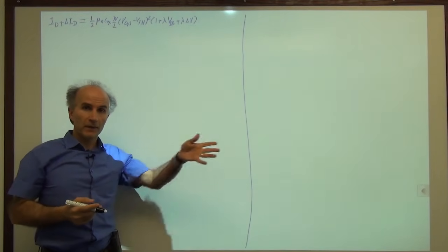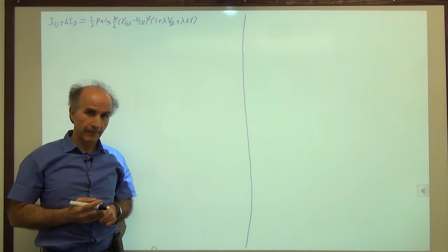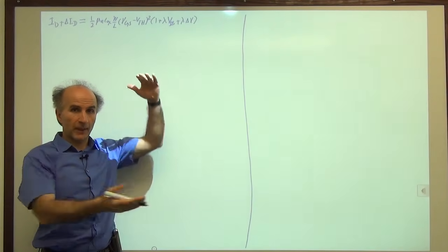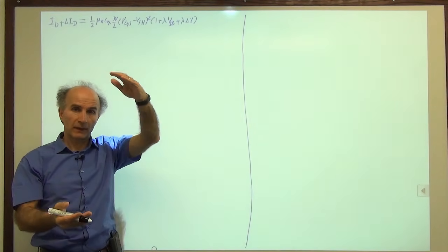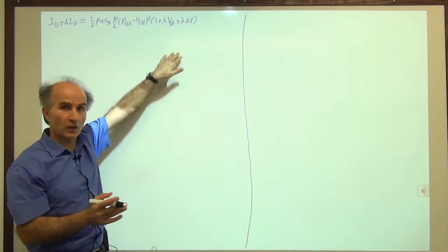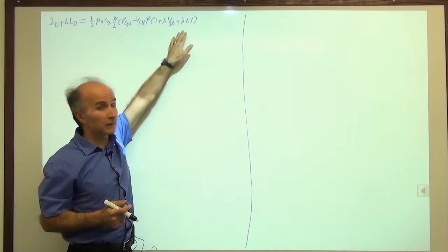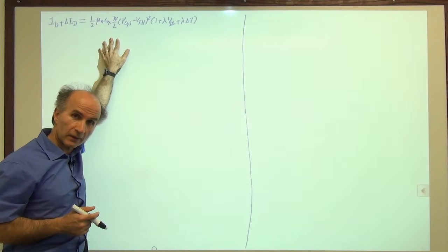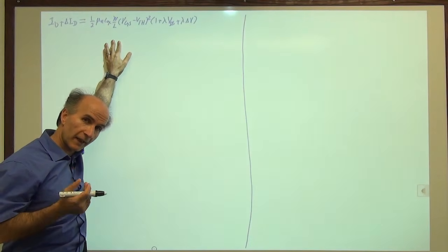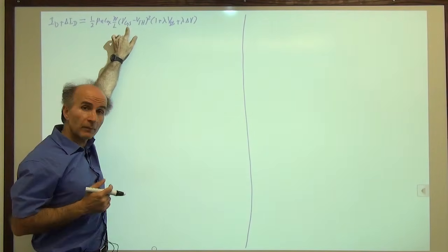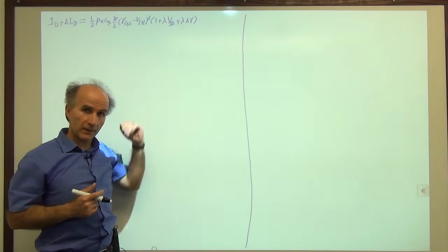Okay, that's exactly what happens in the circuit that we had a minute ago, right? We are just looking at the general case. We have a battery between gate and source. We have a battery between source and drain, and we increment that battery by delta V. All right, this is the general equation. This is the large signal model, if you will. Even though the changes are small, I start with the general equation. If you remember, last time when we derived GM, we also did the same thing. We assumed that VGS was incremented by delta V and then simplified things, and GM popped out. So it's the same situation here.